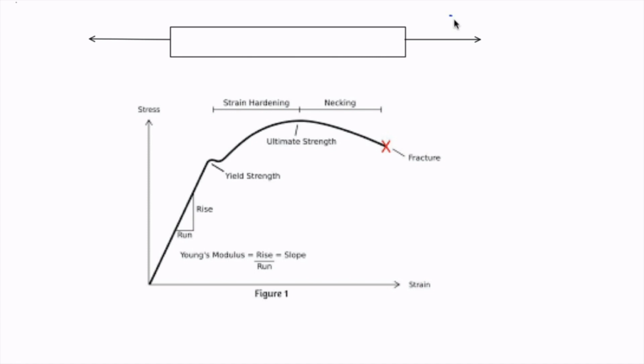Suppose you have some load X on both sides, and when you keep on increasing this load, what is going to happen is shown in this graph, of stress and strain, strain on the x-axis, stress on the y-axis. At the beginning, when you try to increase the load, it will obey the stress-strain relationship in a linear way, stress directly proportional to strain, and after that the proportionality changes